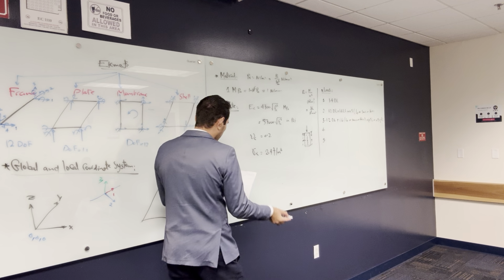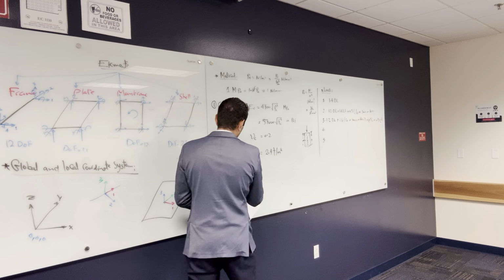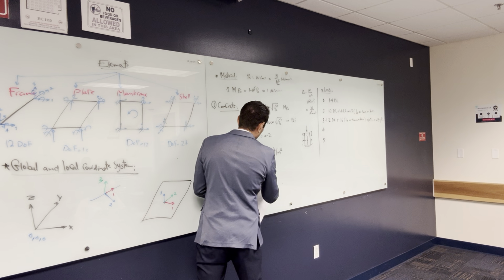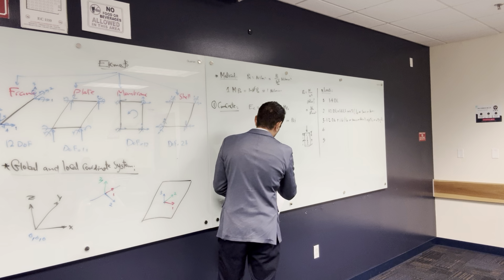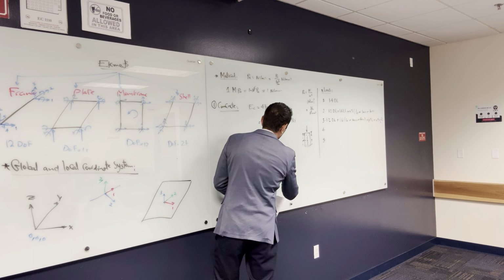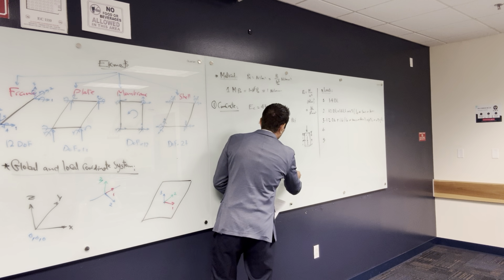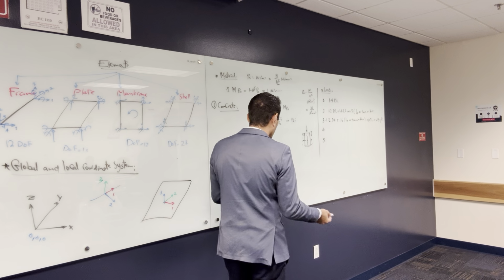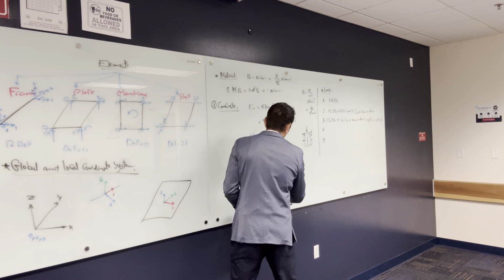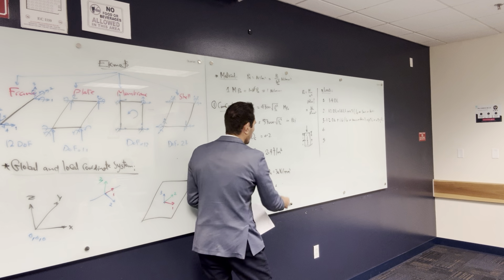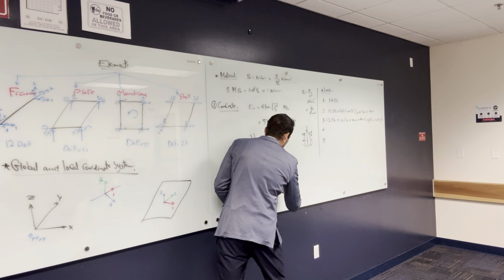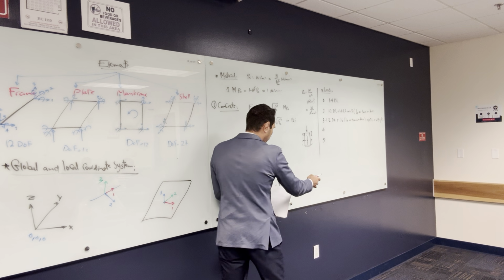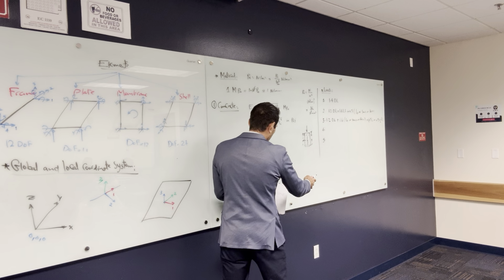All right, so that's the regular concrete material characteristic. Let's say I have concrete 30, that means the compressive strength of the concrete is 30 megapascal or 30 Newton per millimeter square. If you want to convert this to ton per meter square, I do it step by step. I have to convert Newton to ton.